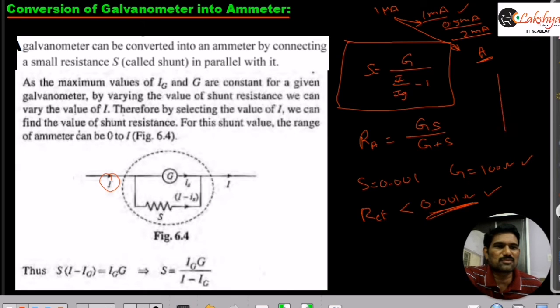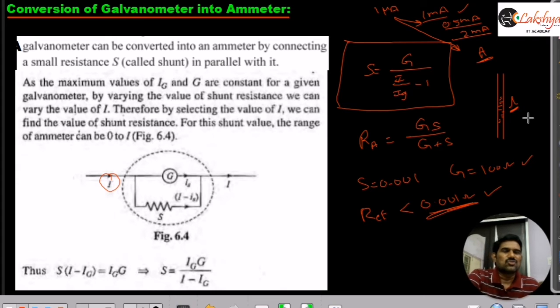There is a mercury column in a small capillary tube. In that small capillary tube, the mercury level is increasing, right? So we are measuring the level of this mercury column. That means what we are actually measuring is length. That length is calibrated, and the scale is calibrated into temperature, either Fahrenheit or centigrade. One division can represent 1 degree Fahrenheit or 2 degrees Fahrenheit. That is nothing but what we call calibration here.